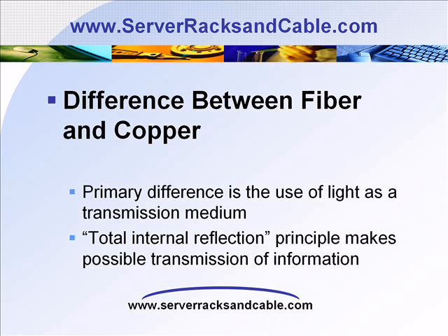The transmitter is used at one end of the fiber optic cable system to originate data coming onto the fiber optic lines. The transmitter accepts information as coded electronic pulses from copper wire, then processes and translates them into equivalent light pulses using ILD, injection laser diode, or LED, light emitting diode. The light pulses will be funneled into the fiber optic medium by a lens.